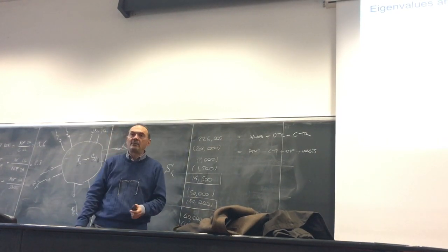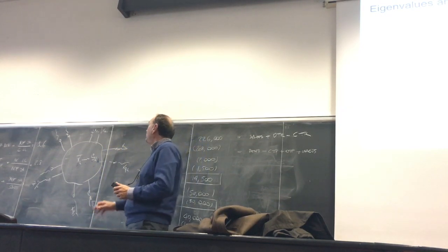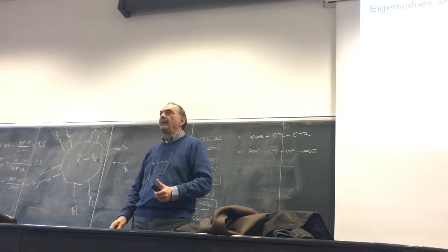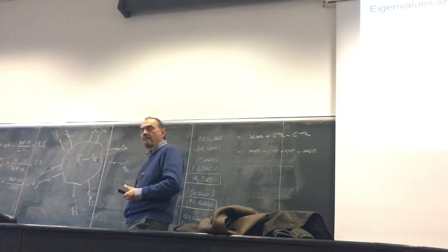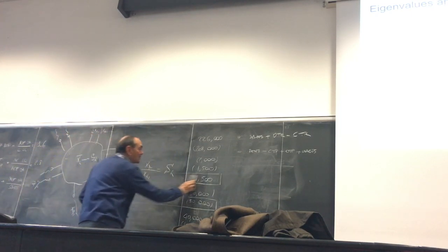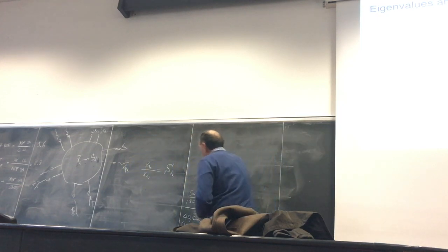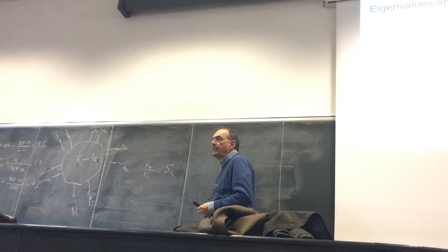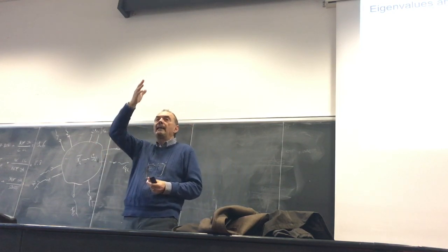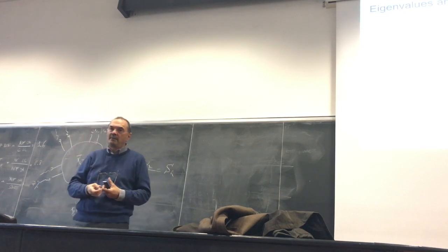For each eigenvector, I can immediately obtain the excitation I have to apply to my network in order to get the first eigenvector, the second eigenvector, and so on. In what way can I derive by induction the eigenvector? Simply by replacing the symmetry plane with an electric or magnetic boundary condition.